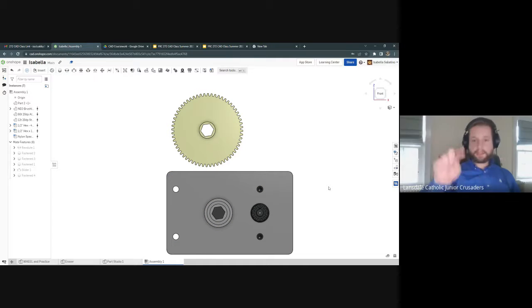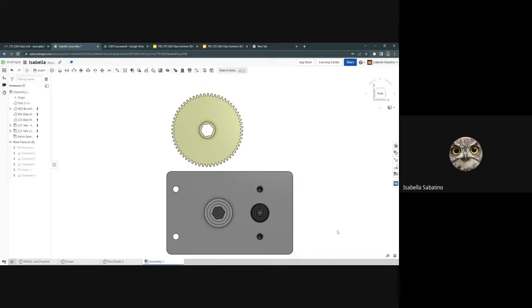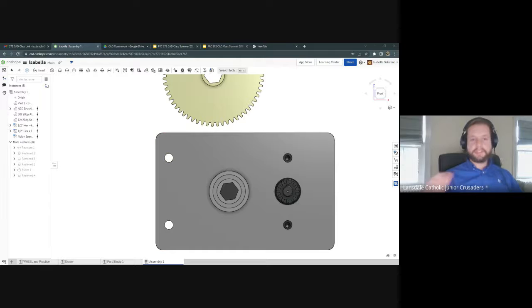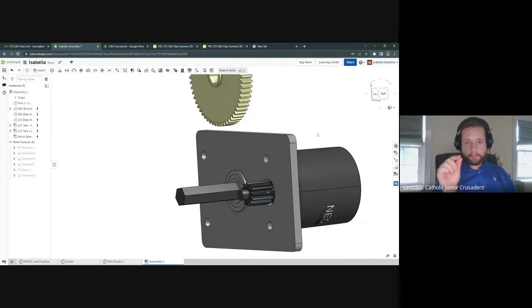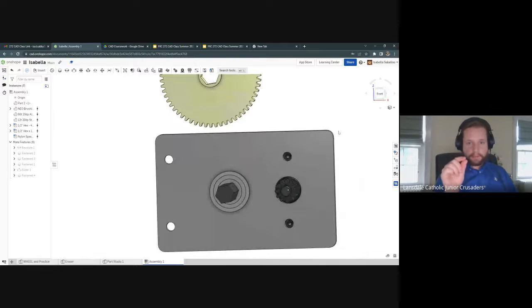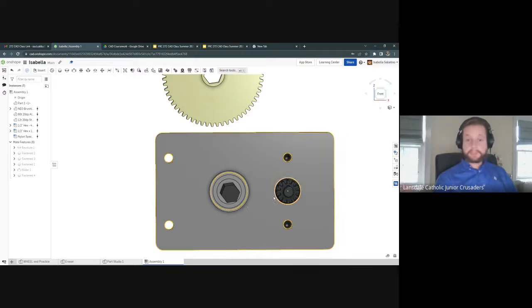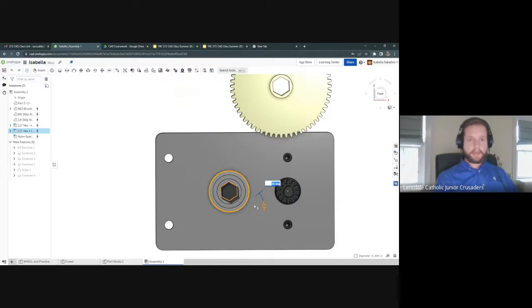And now try to click the plate and grab it and move it. It's not moving. Good, because it's fixed to the origin. The origin is kind of like the starting point, and it's the only point that doesn't move in space, in your model space. Everything else, if you don't tell it to be fixed anywhere, it can move anywhere and at any time.